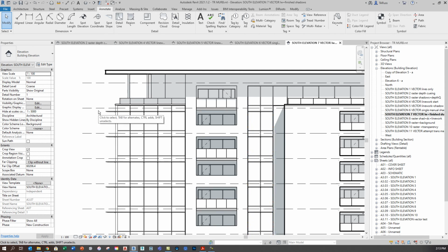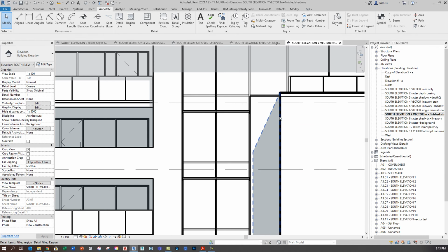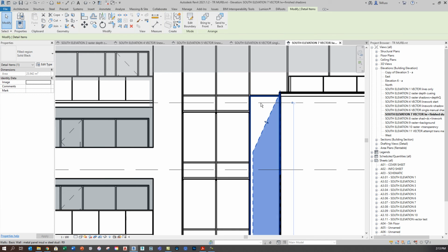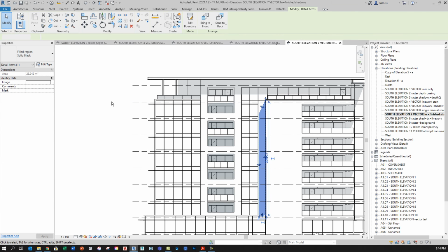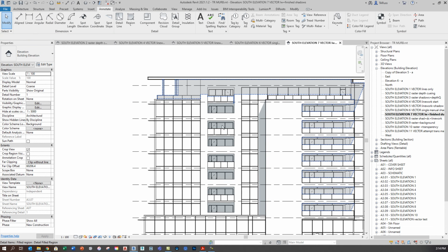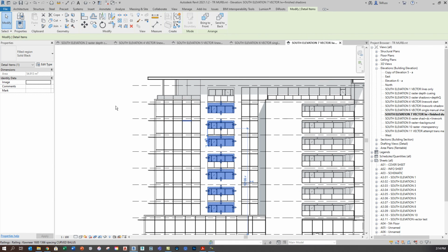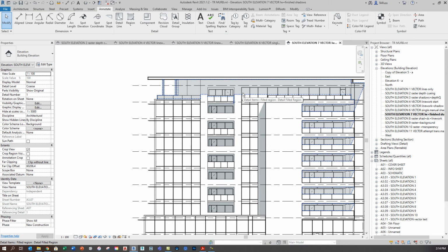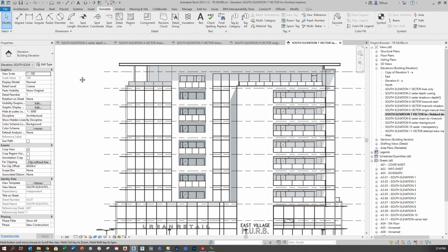So I've added some emphasis there, but more importantly, I've used the Linework tool to boost some foreground elements and differentiate them from background elements. And then I've added these manual shadows. And what's interesting about this manual shadow approach, as I click on the elements that I did add, is that you can actually add a little bit of color to this. Not sure why you would need to do that, but the option does exist. It'll still allow you to apply some color or some different tone and maintain the vector quality of the lines, which is one of the rare cases in Revit where it will allow you to actually generate some vector color.